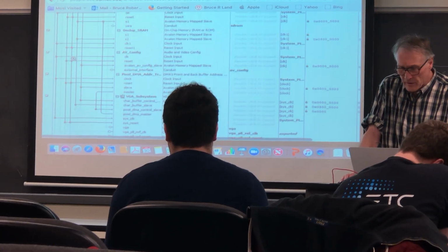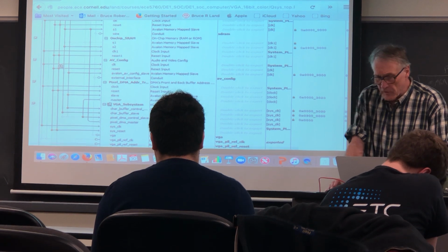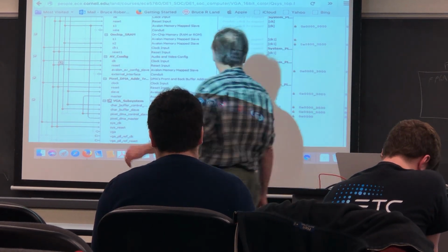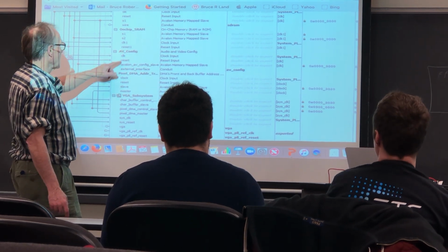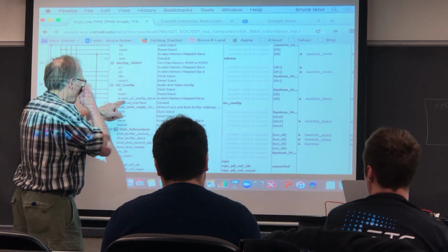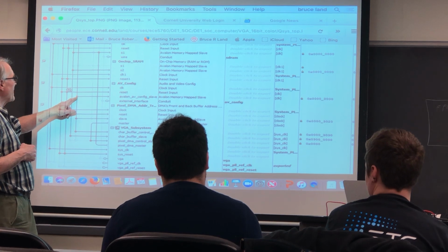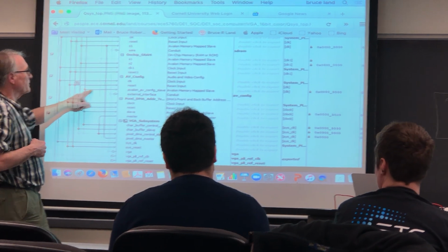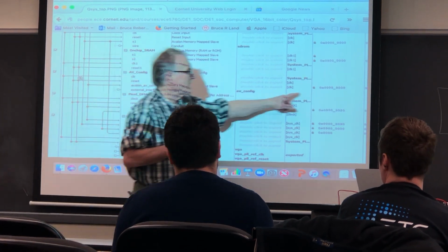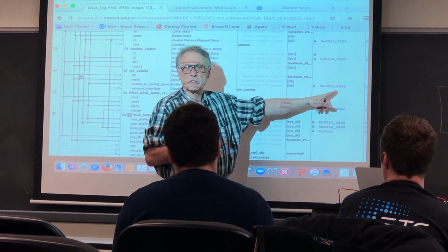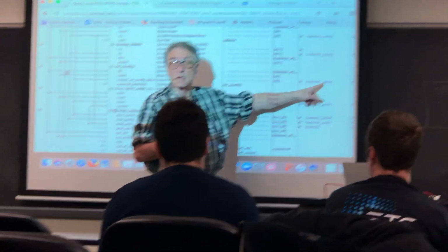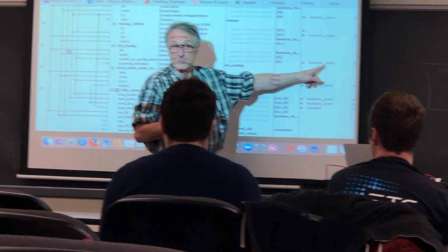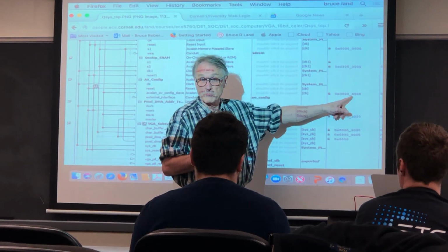On the other hand, we go down to the AV config module. This is on a separate master. This is on the lightweight master, and that has address 3000, because it's a different master that does not overlap SDRAM memory. It's a different bus.